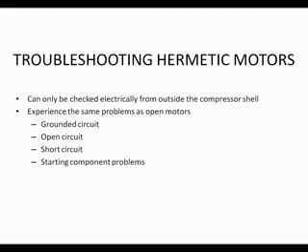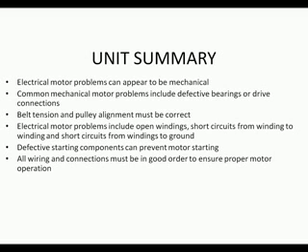Wiring must be in good condition for motors. Loose connections can cause system problems. It can result in oxidization on electrical contacts. Oxidization can increase circuit resistance. Resistance increases the amount of heat generated. It can result in low voltage being supplied to the motor, and low voltage can result in increased motor amperage.